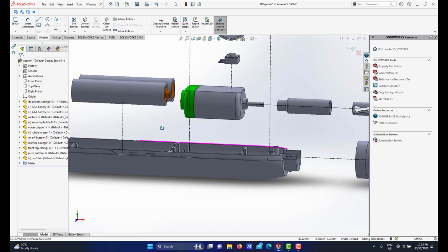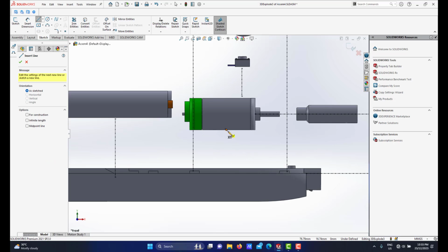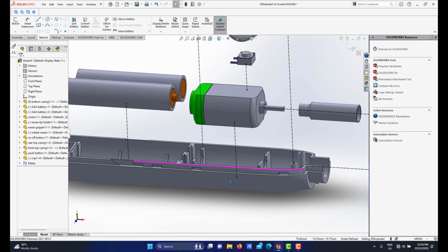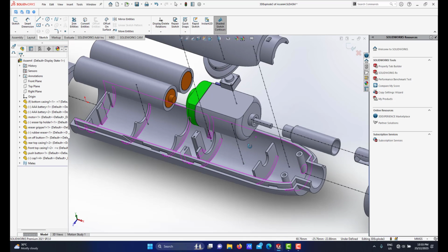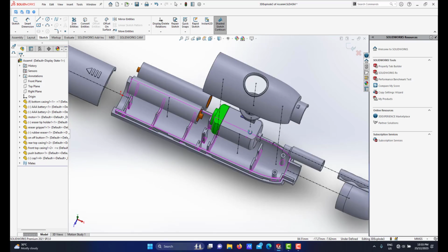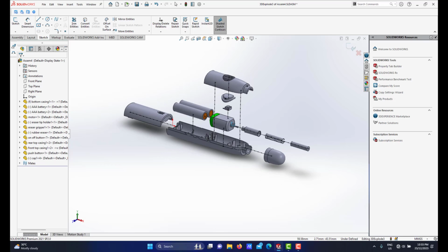I'm under the jog line here, so I go back to front view and just draw this line. I just draw a straight line up until it shows that the motor will be mounted to this position, to be really supported by these two ribs. Right, so I believe these are all the path lines that need to be shown.